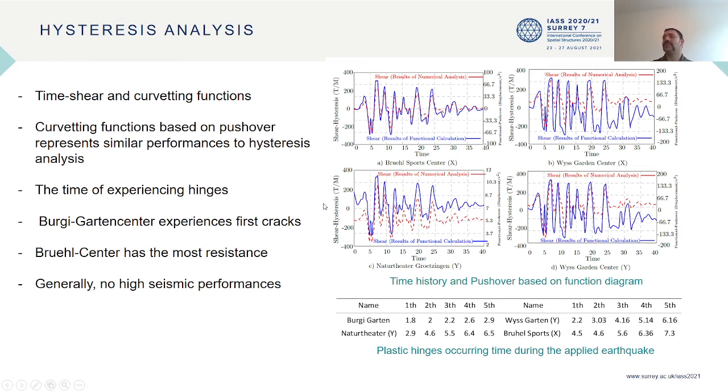The other evaluation related to hysteresis is assigning the deformation on the top center of each shell and recording the amount of shear at the support. That's similar to pushover, but based on the spectrum, we applied the deformation on the top center of each shell.